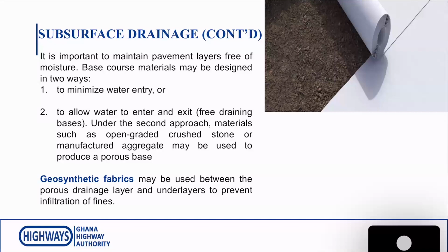it's like you are trapping the water in the pavement. And there's a typical example in Ghana that caused a major problem where we have a crushed stone base, but the shoulder is a natural gravel material. So all the water that enters the pavement could not be drained away, and that led to early failure.